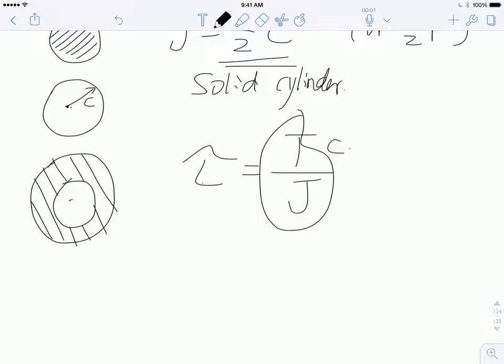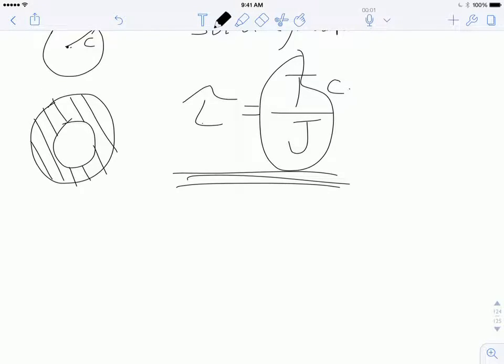So what is the shear stress inside here? Chances are, at the rotational center, it's 0, right? And then the shear stress here is very small, and it becomes bigger and bigger with the increase of the radius, right? So that tells you if your material is undergoing torque, the material in the middle has no or very small amount of shear stress. Therefore, that material does not carry much load, so we can just use the hollow tube for the application we want. Make sense? Because of this equation, the material in the center does not carry that much load at all.